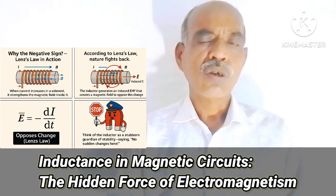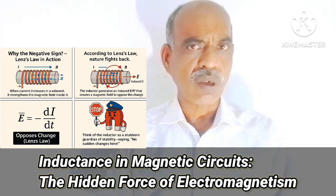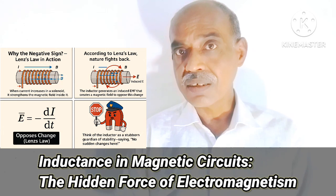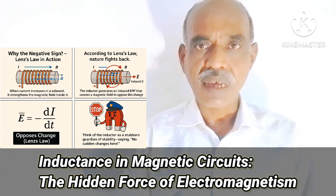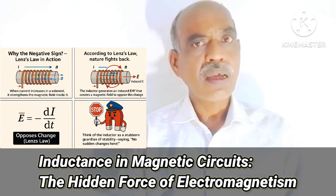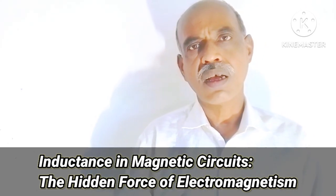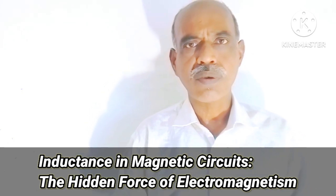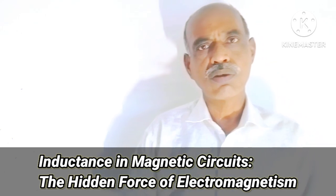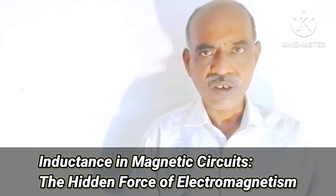I was talking about this phenomenon. That's why the negative sign is there. The reason for the negative sign in the expression is that fact. From here also L can be defined. You can see that induced EMF is equal to minus L di by dt. Therefore, L is equal to induced EMF times dt by di.